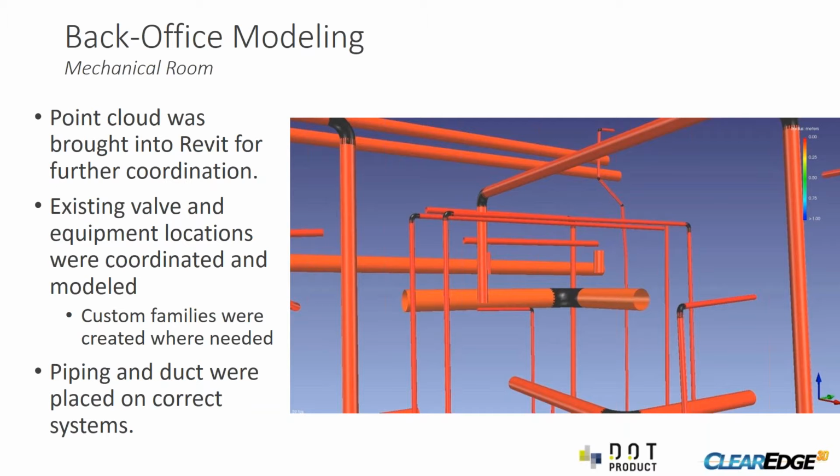Within Revit, we also, at this time, went through and put all the piping and ductwork and everything on the correct systems that they needed to be on, so our design team could go through and do their tagging and start the demolition and new work.